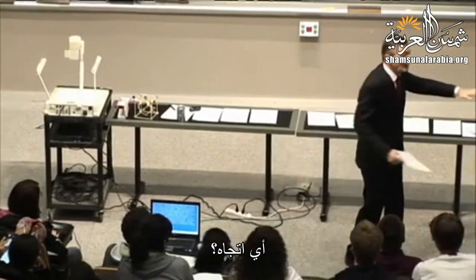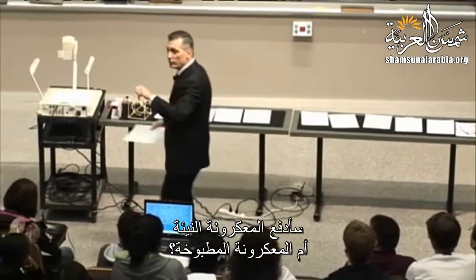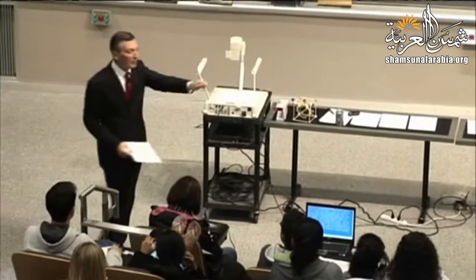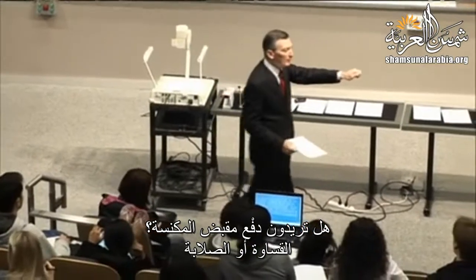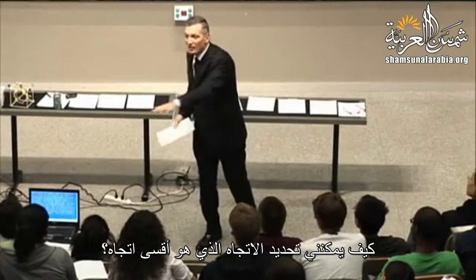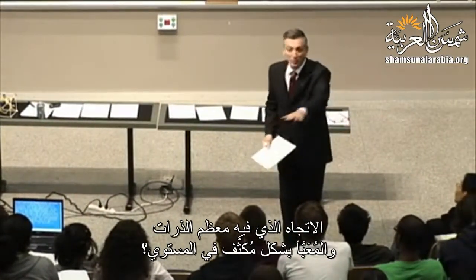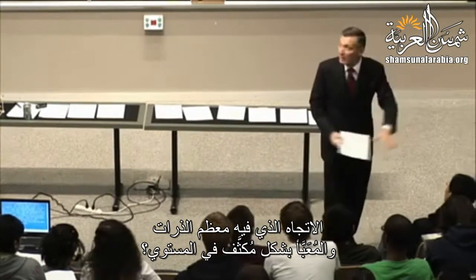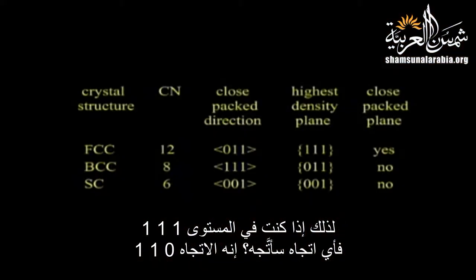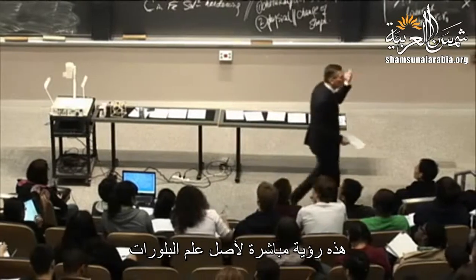Which direction in the plane? Any direction? I'm going to push some pasta. I'm going to push uncooked pasta or cooked pasta. You want to push on a rope? Or you want to push on a broom handle? The stiff one. So how do I determine within the plane which direction is the stiffest direction? The one with the most atoms, which is the close-packed direction when I'm in the plane. So if I'm in the 111 plane, which direction? The 011 direction. So this is direct line of sight from the original crystallography.